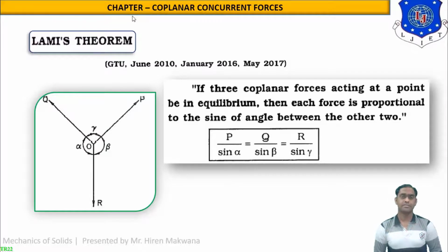Today's topic is the most important topic, that is Lami's theorem. Now what is Lami's theorem? Whenever three coplanar concurrent forces are acting simultaneously on a particle or on an object, but the body still remains in equilibrium, meaning the system is in equilibrium under the action of three concurrent forces, then Lami's theorem is applicable. And what is the use of Lami's theorem?